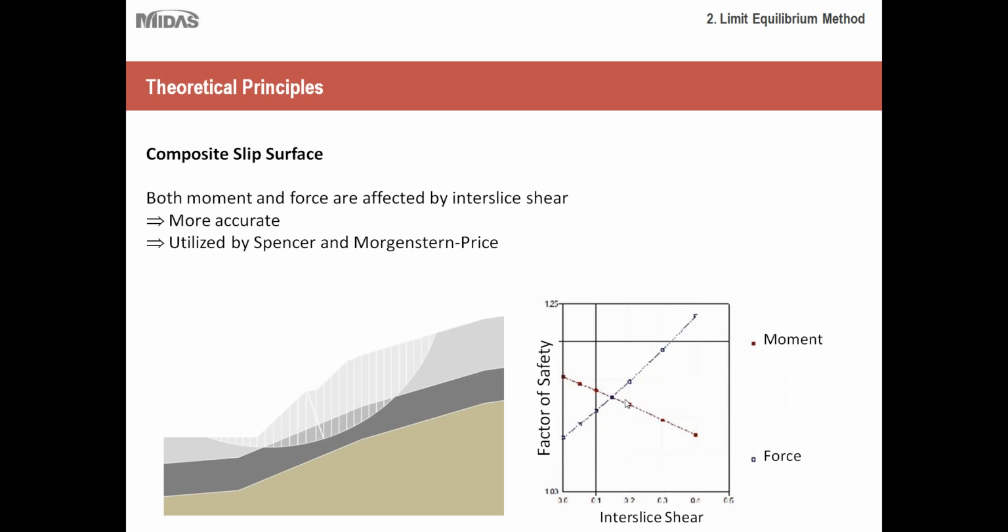Whereas if you were to apply any sort of lateral or transverse loading, the factor of safety would increase, naturally, because there'd be a certain amount of resistance coming from this area here, keeping the slope stable. So that's another thing to keep in mind when you're creating your slope models. Typically, it's a good rule of thumb to go a little bit beyond the base point, so that you take into account this area here, because that's subject to failure as well, or subject to being a part of the slip surface.